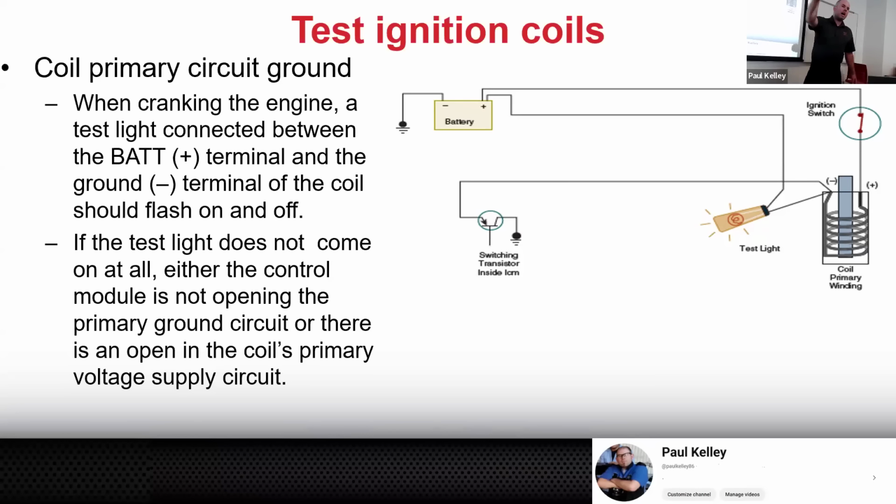Yeah, when you turn the key on in an older car that was carbureted, it would literally just give power, positive voltage, to the coil. And that would mean it's ready to start, right? So when you see the movies where they're hot wiring vehicles, honestly, all you needed to do was get positive voltage from the battery and send it to the primary of the coil. And that car would run right now. That's what hot wiring was.